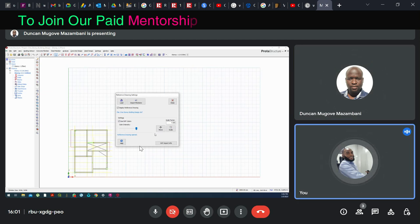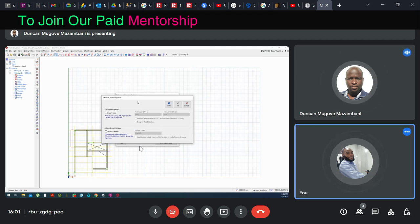Now we want to import that grid line and the column axis into this place. So they will now convert to column elements and also axes. So click there first. Import members. Then check import axis as grid and import column as column. So check those two. Okay, that's fine. And then click on OK.